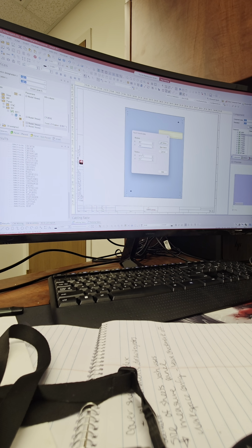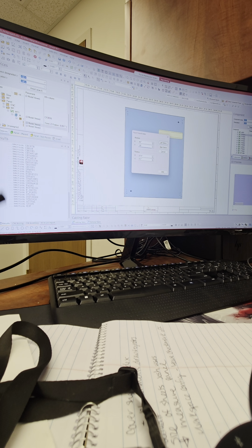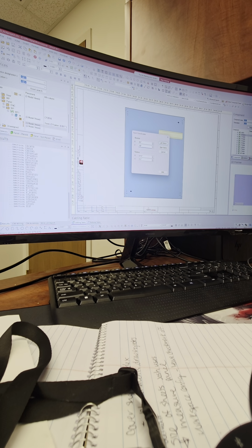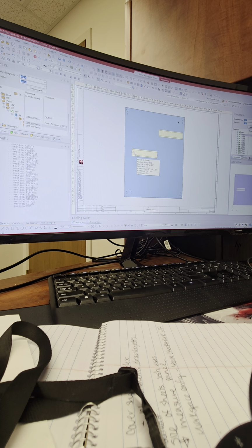Right, 10 inches. And the X1 on the top, if you see the ruler all the way on top of your screen, that is your 80 inches ruler as a place in space. Again, why it's 80 inches right now, I think it's our initial placement, probably our sheet was not at 0, 0 when we started. But what you just did is proper, and you would have just clicked the left button to place, as in using these two references, two rulers, to place something at a very, very specific location.